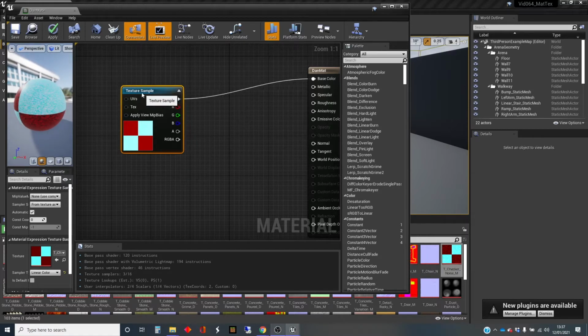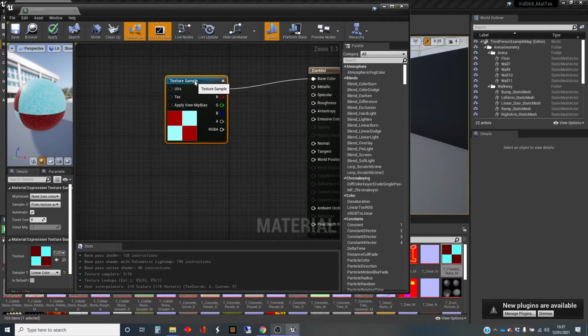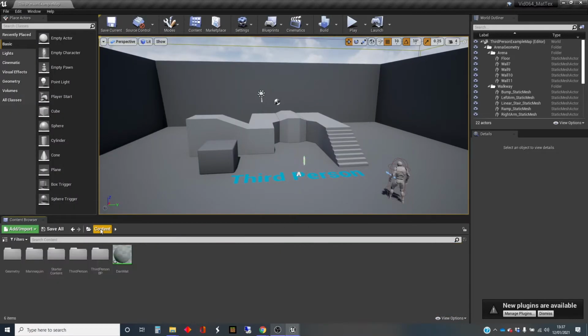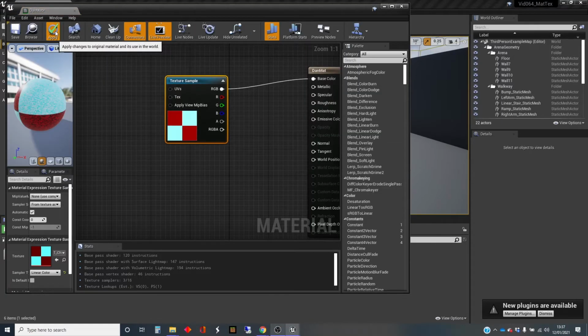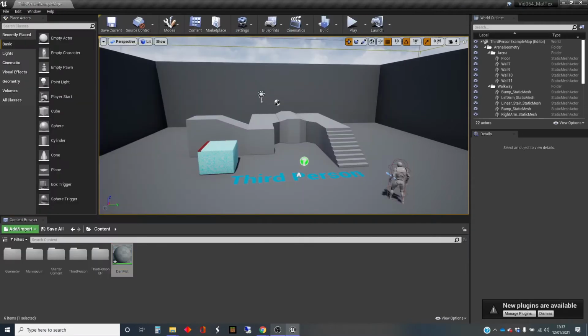I'm not going to mess about with the light interaction here, with the specularity, etc. The texture is what I really want to look at. So at the moment, we've just plugged that texture straight in to there, and I'm going to go up to the material. Now, I haven't applied the material yet. I'm going to stick it on this box. Go back into it and click apply. I'm going to work it out, and hopefully it'll appear on my box. Right.